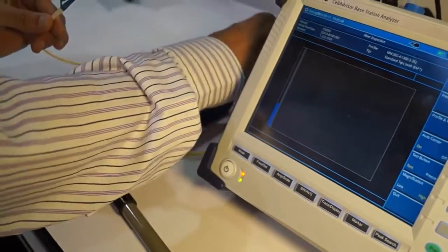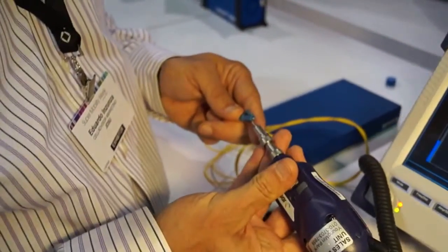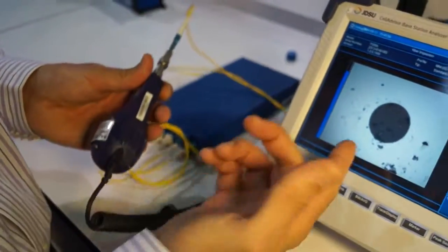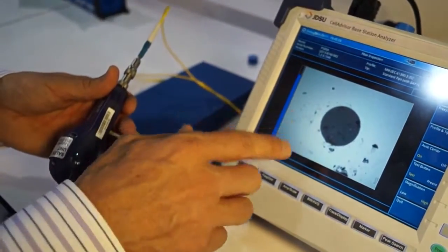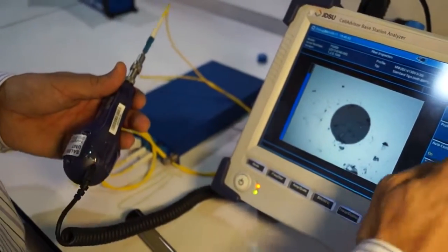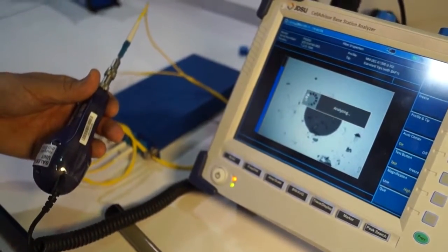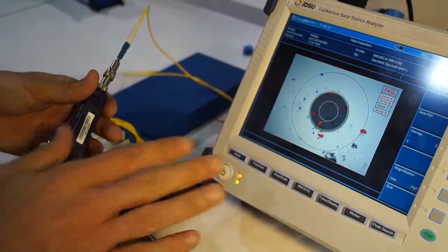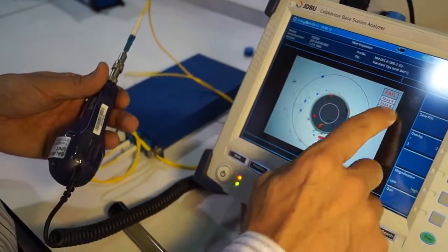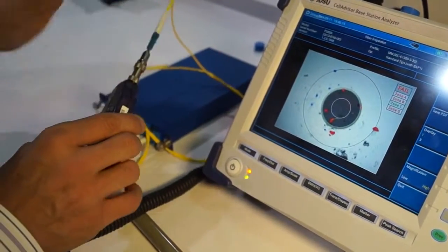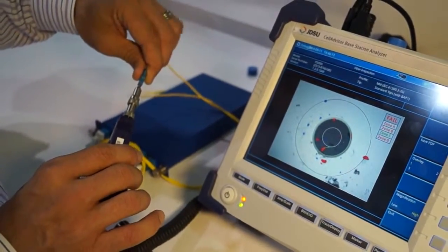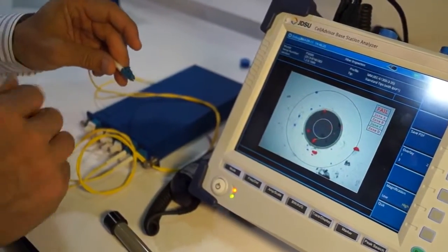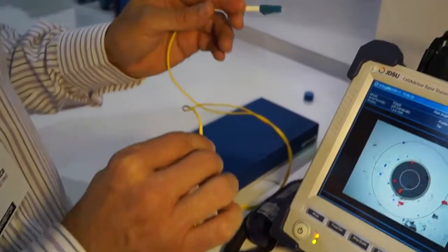So that is the ability to look into the connectors and see how clean the connectors are, because most of the time what happens is that we might have something like that, which is dirt around the core of the fiber. So when we perform the test of the fiber to see how clean that is, automatically the instrument is going to be making all the tests and is going to be indicating in which zones we have dirt on it. So this is the first physical type of test that is being done. Now, when the fiber is clean and checked, the next step will be to analyze the signal.